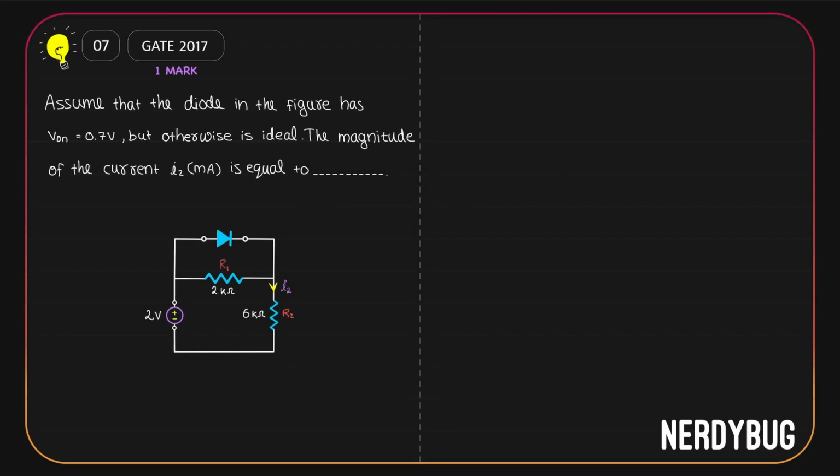Now, the first thing we have to do is check if the diode is on or off. For that, we'll do the same trick again. Assume the diode is off and remove it. Then find whatever is the potential we get across the two terminals. If it is sufficient enough to switch on the diode, then we can assume the diode is on. If it is not enough, then the diode is off. It's that simple. So let us check if the diode is on or off.